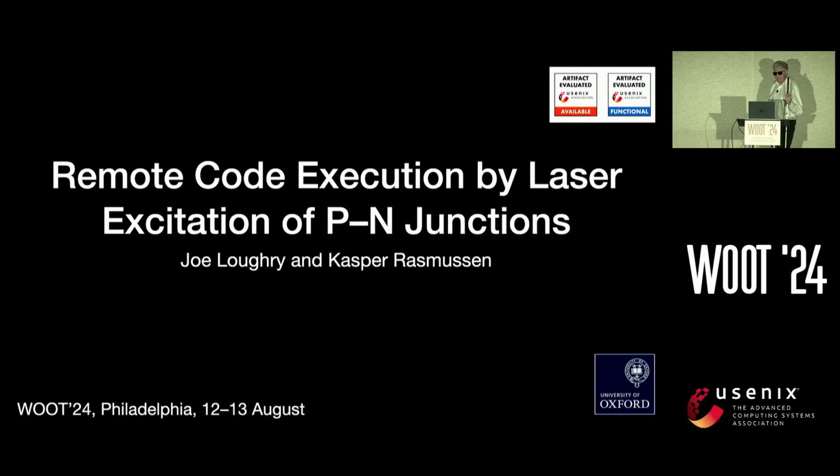Okay, the context here is status indicator lamps and why you might want to go around shooting lasers at them. If you shine a really bright light on them, all that energy has to go somewhere. Would you believe it flows backwards into the electronics? Effects range from nothing at all to remote code execution.